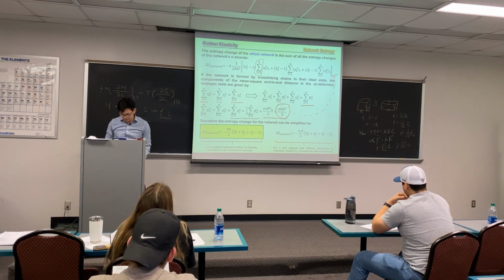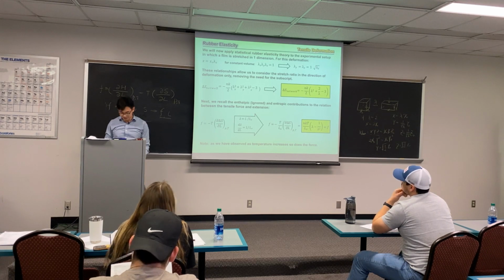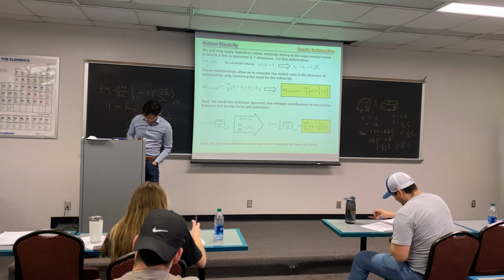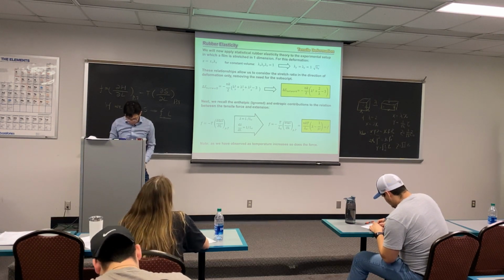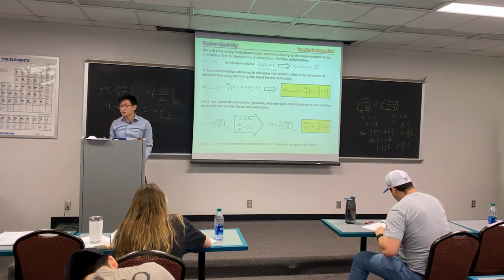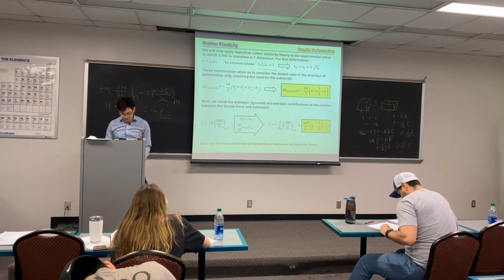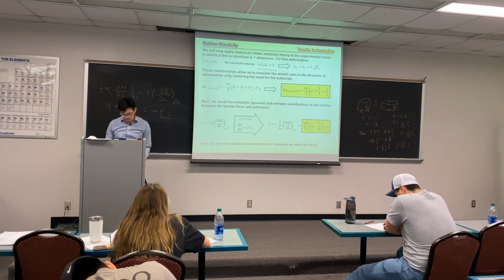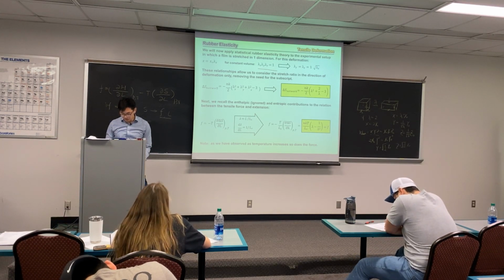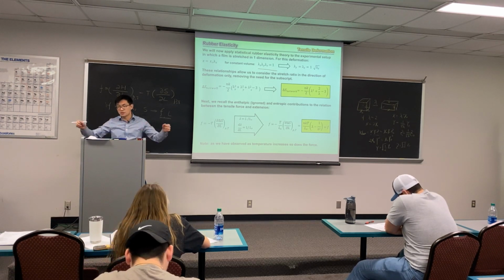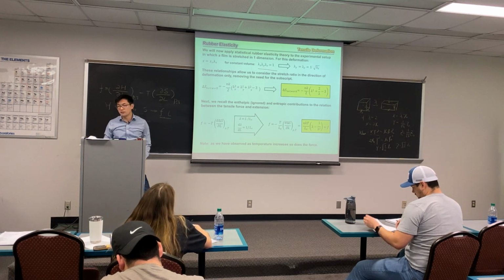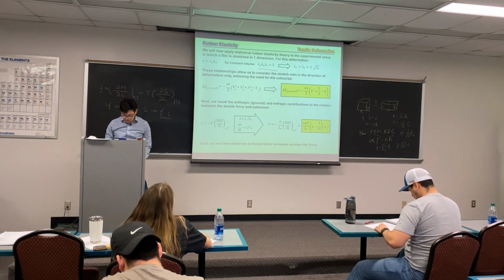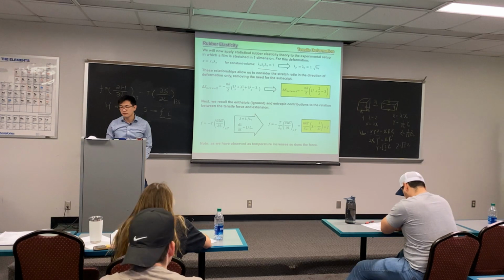Okay, we finished 25%. We have explained quite clearly how all the lambdas relate to each other. The draw ratio in the x direction, y direction and z direction, if we assume it's just a tensile deformation in one direction, because of the constant volume constraint, all these multiplied will equal 1, right?